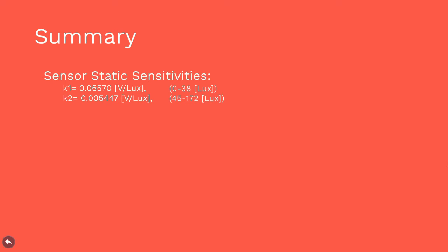The static sensitivity in the range of 0 to 38 lux was found to be 0.05570 volts per lux. The static sensitivity for the range of 45 to 172 lux was found to be 0.005447 volts per lux. The sensor time constant was found to be 0.172 seconds.